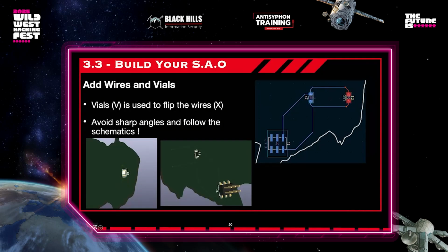The vias are the little holes that you see sometimes on the PCB. They help to pass the wire from the back to the front, or from the front to the back. So as you can see here, or maybe you can't see that very well, I'm on the front, so I'm putting a wire here, a via, and then it's going to go through the back and connect to the resistor. And yeah, make sure to plug everything. Don't forget.